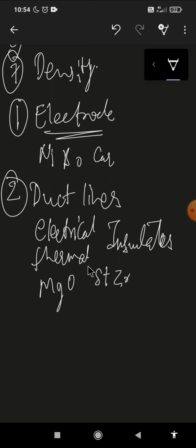MHD ducts have to withstand a temperature in the range of 3000 degrees Celsius. Presently, steam cooled walls made of insulated laminations of very thin nickel or stainless steel have been tried. The research is on to use suitable ceramics or coatings of ceramics as duct materials.